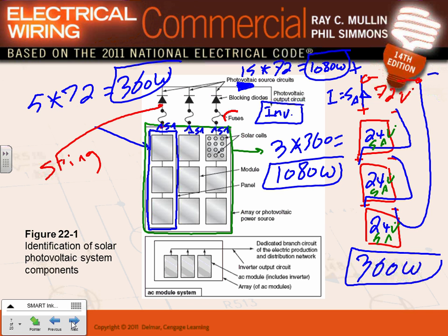Do you have to have a fuse? Can you guys see that there is a fuse here to protect the DC string right here? You have to protect it with a fuse. There are also diodes, Jeff, and the diodes here are to protect this panel from feeding current into the next panel, or one string from feeding current into another string. Say you have a short circuit right in this panel. Do you really want the other panels to dump power, coming from here and going right in here? You don't want that to happen.